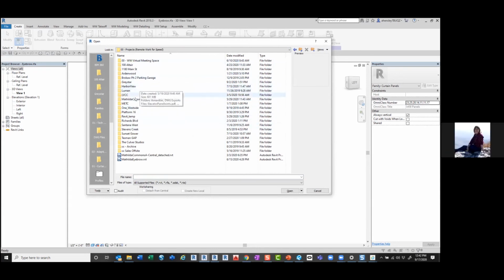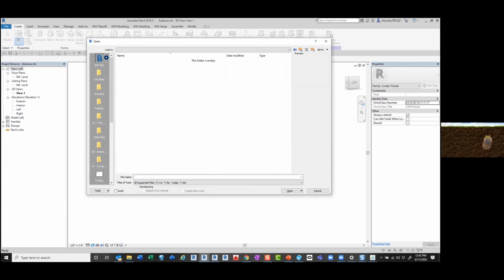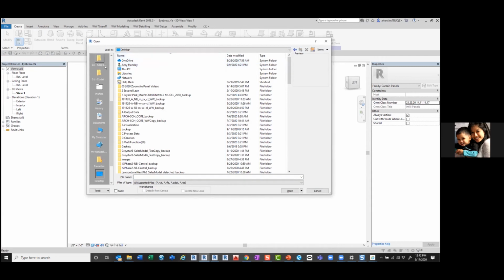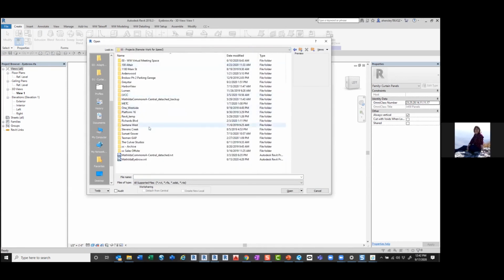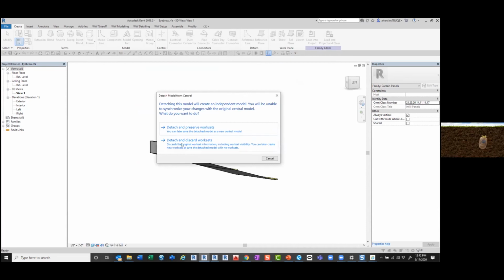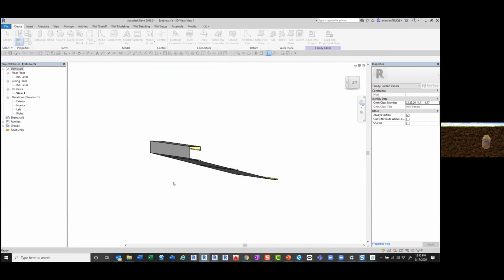Then is there some way to... We can't tell what mark number goes to which panel. Right, and you have to have the elevations in your shop drawings for your panels. What if there was a family made of 3 different families? Then would the mark numbers be easily separated? No, it's still one tag. It's still one object, so when you place the tag on there, it's just going to read the mark numbers as one property and just display it.